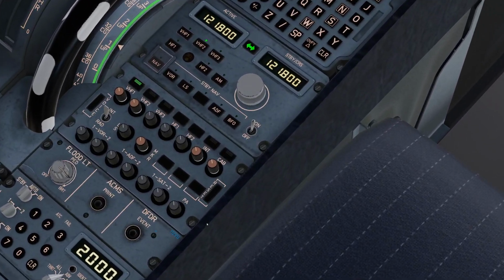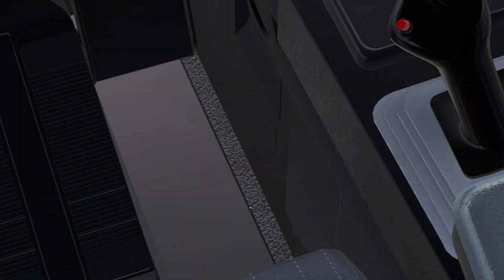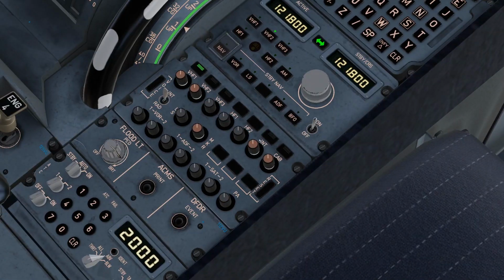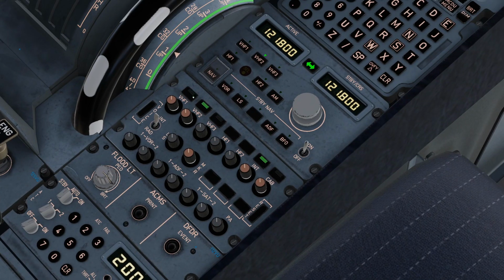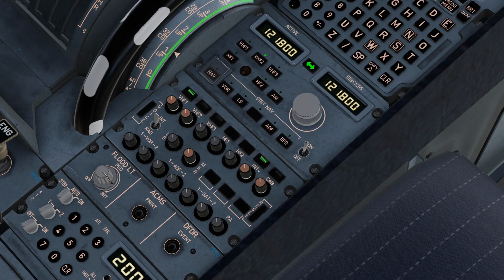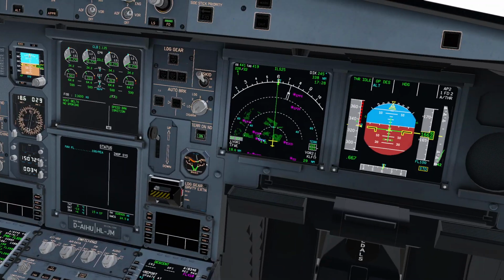Apart from that, when something like this happens, the microphone of the oxygen mask is going to activate automatically once you take the mask out of the storage. However, it is still a good idea to go to the interphone. What's this doing? That's not how it's supposed to work. So it is still a good idea to go to the interphone, and most importantly, take the PTT switch out of the interphone position. So, like that, your colleague does not constantly have to hear Darth Vader on his headset when you are trying to breathe.